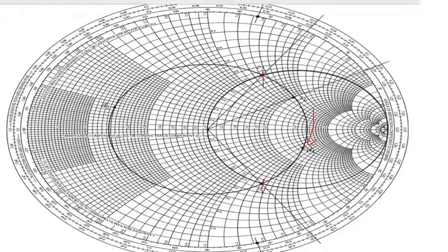So this in Z of lambda value, it is coming 0.327. It is given in your notes also. It's coming 0.327 lambda here. And your ZL point already I have told you in terms of lambda was coming 0.209. So D1 as marked here, I'm just marking it for you all outside, is here. So what is D1? Somebody asks you, it is nothing but greater minus smaller. So you will just find in clockwise direction this D1 point over here, whatever value you got, you have to subtract it from this ZL value. So that value is called as D1.